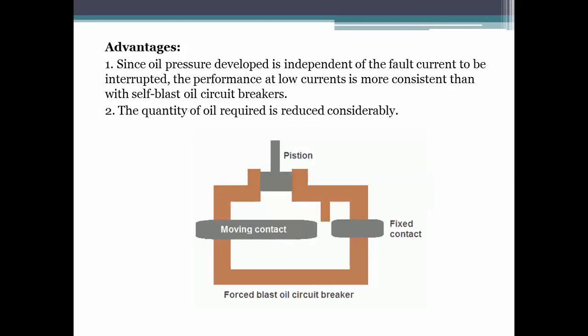So this force blast oil circuit breaker has some advantages. That is, since the oil pressure developed is independent of the fault current to be interrupted, the performance at low currents is more consistent than with self blast oil circuit breakers.